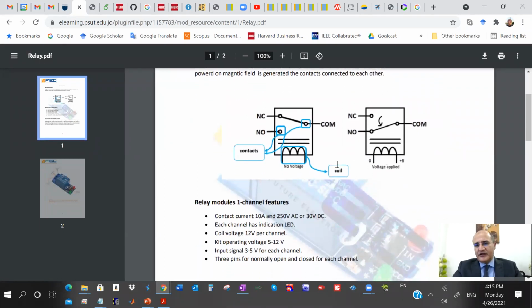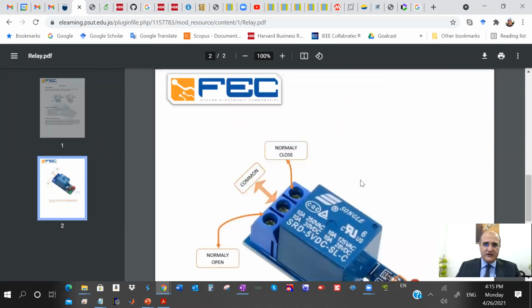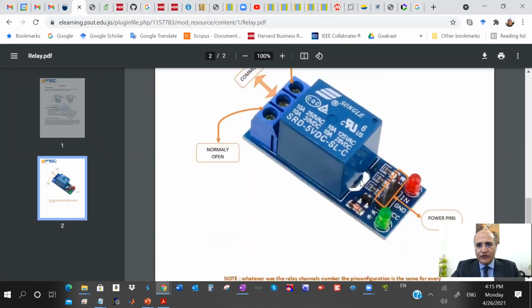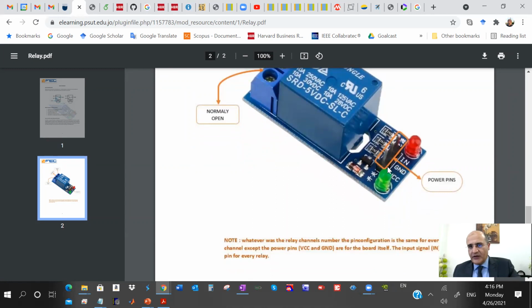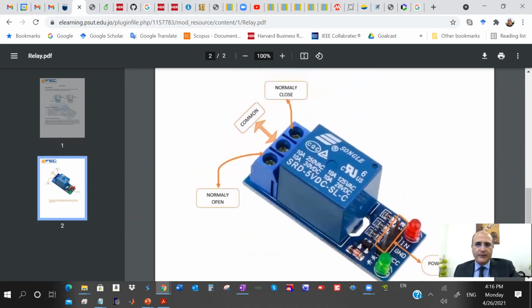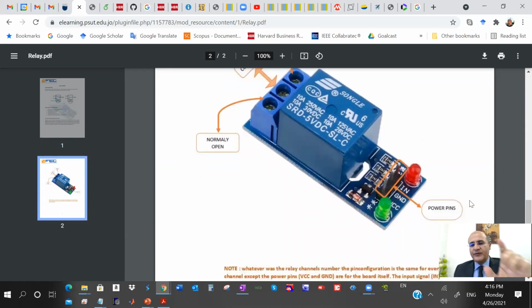Okay, so this mechanical relay usually has 3 pins. It looks like this. This is the actual same one. So you have the control part. You see my mouse, right? Ground is ground, N and VCC. So you take this ground to your controller ground, because the message you'll take it from the microcontroller, right? And the ground of the power source powering your device. Let's say the device is, I don't know, a big motor that you need to turn on and off, a fan or something.